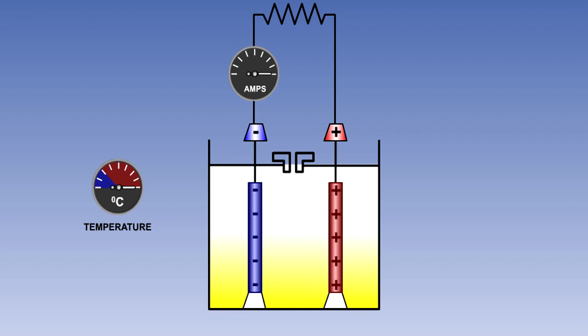The performance of a lead-acid battery is affected by its temperature. With a low battery temperature, the rate at which the battery can be discharged is decreased because of higher internal resistance. In general, the battery performs better when it is kept warm.